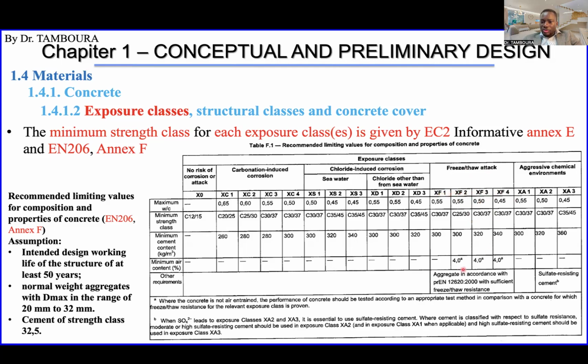Other requirement for these XF classes, you have also the aggregate, okay? The aggregate you need to mix with the cement and water to obtain concrete. These aggregates should be in accordance with this code and should have sufficient freeze and thaw resistance.